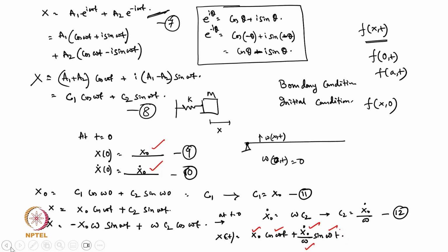in the last class, we assumed that this is mass and this is stiffness, but we considered that our system does not have any sort of damping. So our main equation of motion was, I'm just writing here, m x double dot plus k x equal to 0, because we are not applying any forces on that. So today we will first write the same thing.